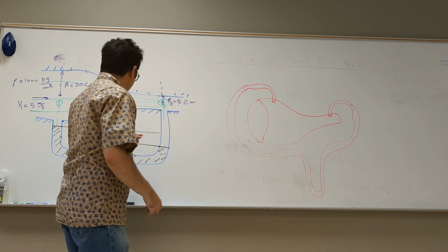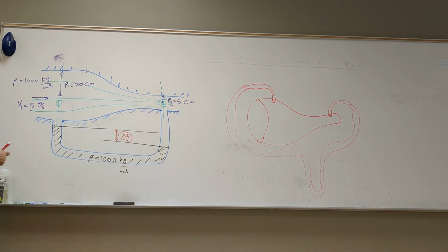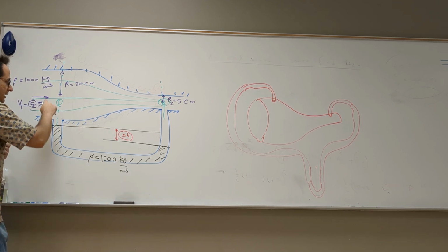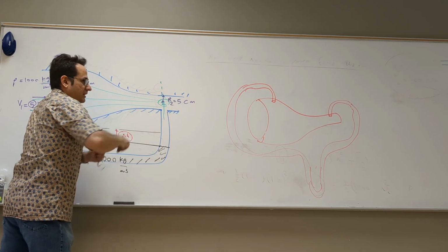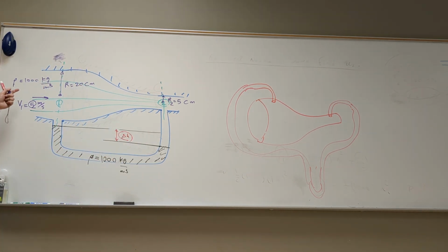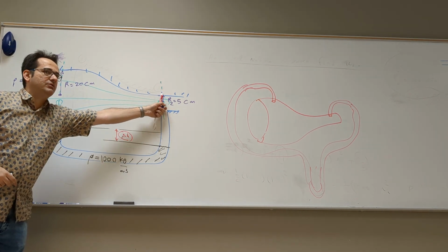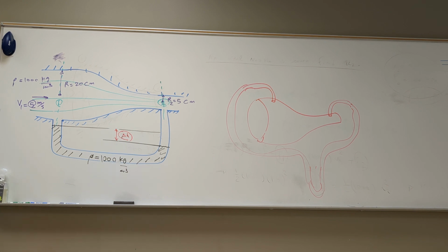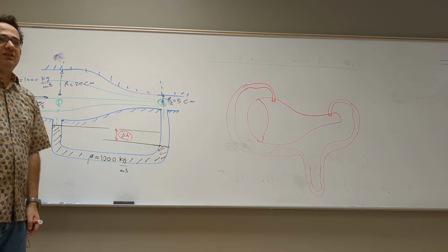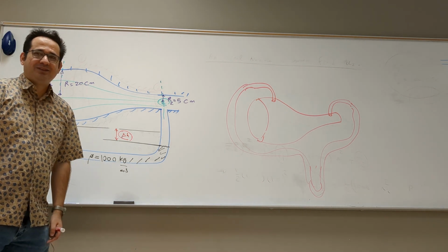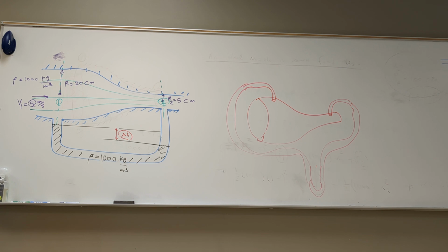So let's say I have velocity here. This 5 meters per second passes through that, and then if I have a converging nozzle, what happens to velocity? The velocity will increase. Whatever you get here must be greater than 5 meters per second. So if the velocity increases, what happens to pressure? Decrease. Why? Can you tell me why? The Bernoulli, right?